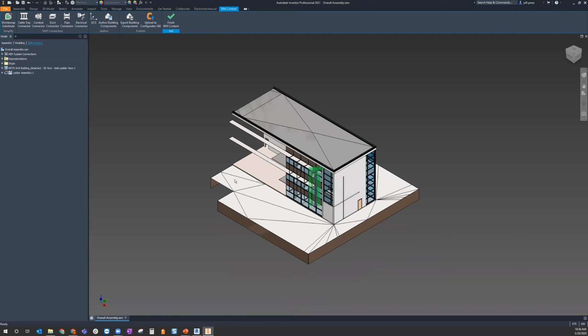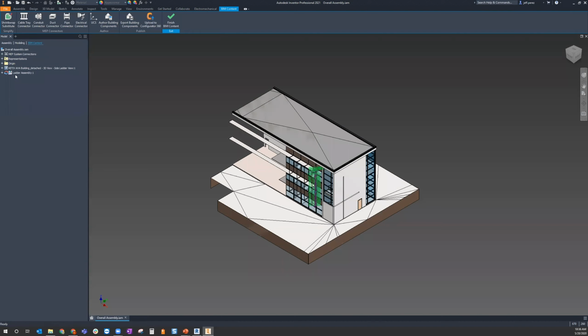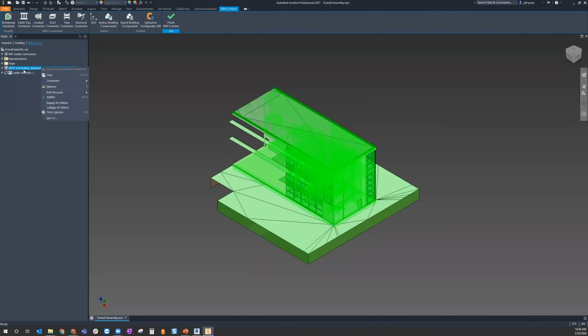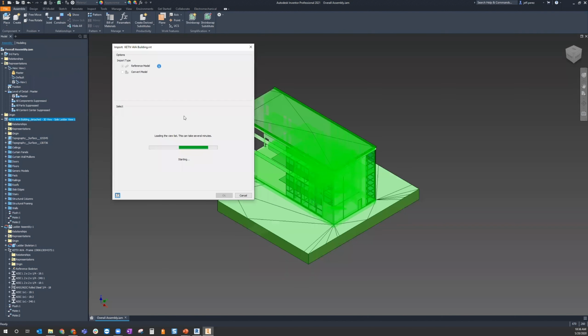I think Matthew had one. Can you bring in multiple 3D spaces, for example, connecting two buildings with a conveyor? So Matthew, one thing about that is, I guess you could bring in another model, but I probably wouldn't do that if you create an adaptable assembly. And why I say that is because you could go back into these Revit files that we have, and we could change the export of this. So let me get out of this BIM content. We can change the import, so I could change what view of the 3D view I was actually referencing beforehand.